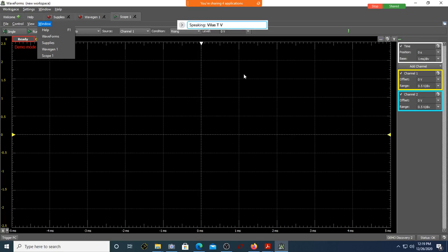Now, since we know that output voltage can go beyond 2.5, you have to set this to 2 volt per division. I'll make both of them 2 volt. Can you see, once you make it 2 volt per division, how many divisions are there from this 0? 1, 2, 3, 4, 5. When it is 5, how much is 5 into 2? 10 volt. That's why you're getting it as 10 volt. Correct?